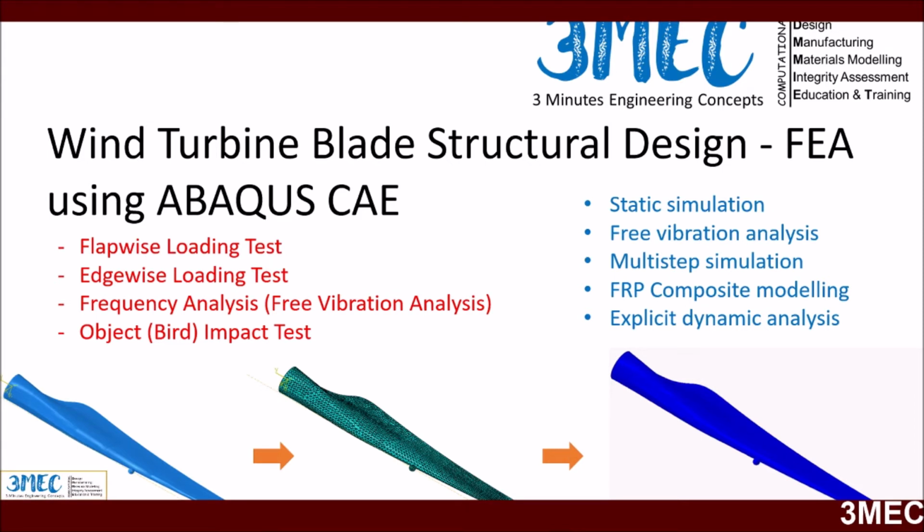So in the first part, I will show you how to perform free vibration analysis to get the natural frequencies of the blade without any loading. Then I will show you how to apply an edgewise load on the blade and perform a free vibration analysis to see the effect of edgewise preloading, and I will compare it with the blade's result without any loading.